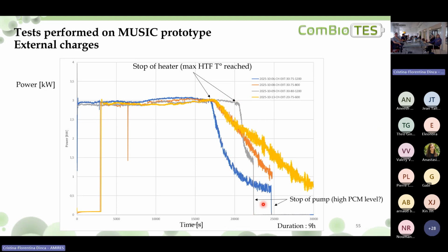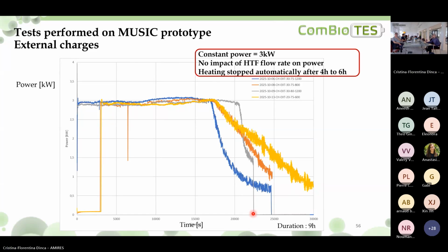In some tests, at some point, the pump is stopped. It stops automatically. We don't really know why. So the power is almost constant at 3 kilowatts. In this test we didn't see an impact of the flow rate of the heat transfer fluid on the power or on the duration of the charge.